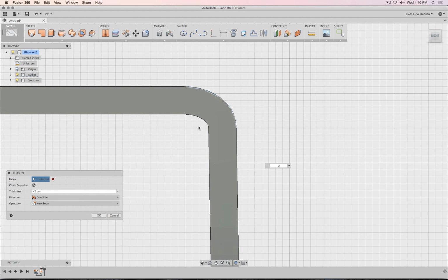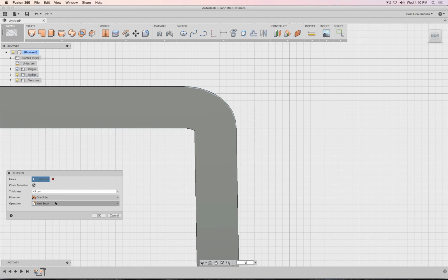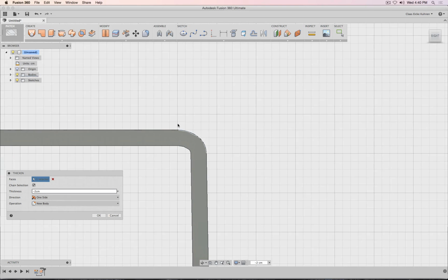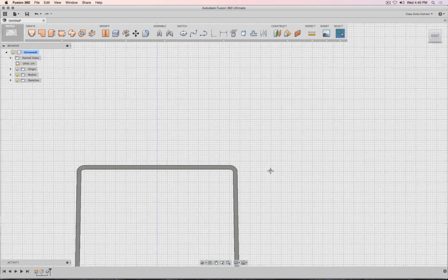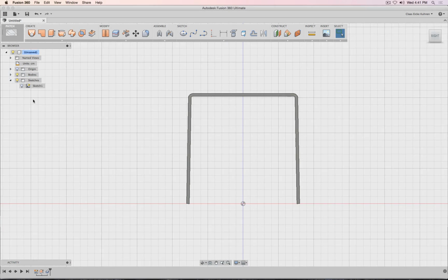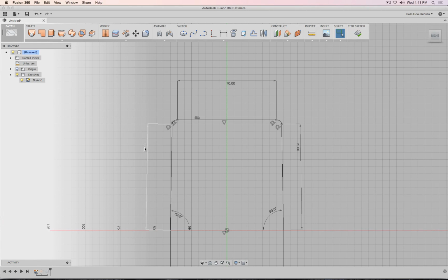Yeah, this should be bent plywood. This would maybe be an issue. So maybe -3. Yeah, bent plywood will complain there a lot. So I guess I would have to make this radius bigger. So here is another nice thing of our sketch engine, edit. Maybe those I push back to 70 and 70 and make this one 65. So we see I have a bigger radius.